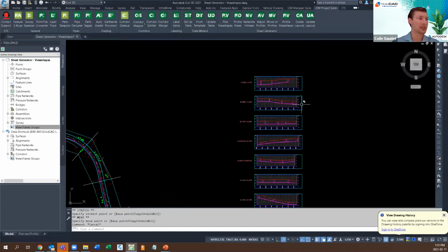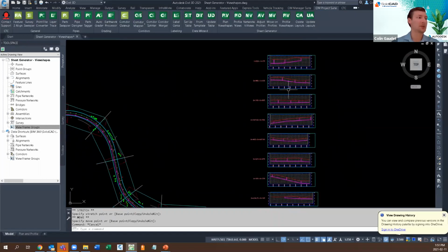And if you take a look here, when I select this, it actually gives you the plan or the profile view shape and the profile print area block in there as well. Same thing as what was happening in plan. Some easy ways to configure all of this. Let's create some layouts now.